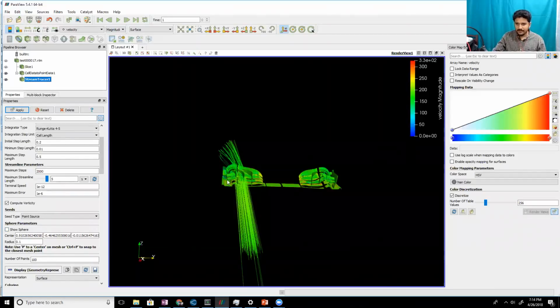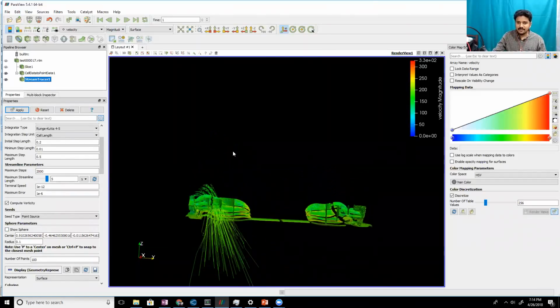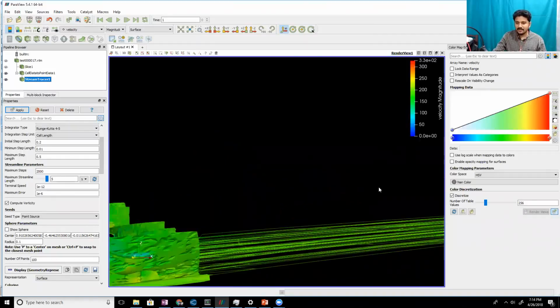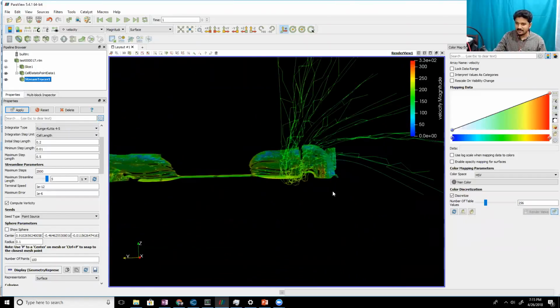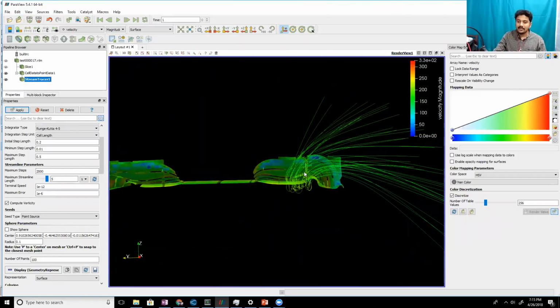Just a second, guys. A couple of features that you observe in real F1 cars are getting captured. You can see how vorticity is generated here, and the flow turns so that it does not directly interact with the wheels. One of the things people care about in F1 cars is the tires that are right behind. If your air is just going through the tires, it's facing them right away. That's very bad aerodynamics because your tires are not aerodynamically efficient bodies.